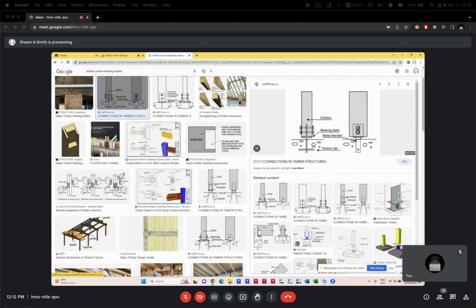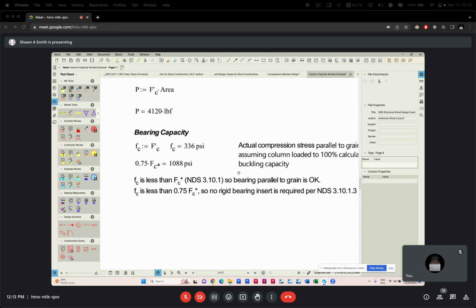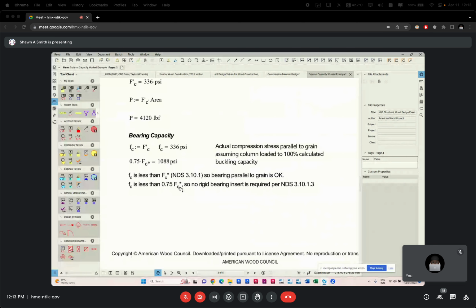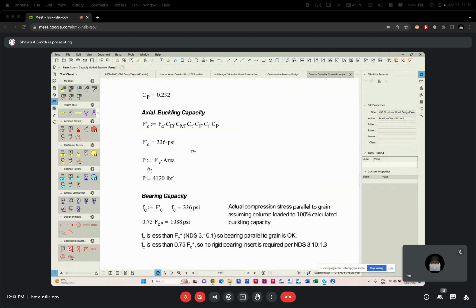It therefore means that you don't want the timber to be, perfect, here's one, you don't want the timber to be bearing directly down on whatever the support is. So you put some metallic inserts now so that the bearing is shared across a metal plate as opposed to just timber. Right? We don't have that luxury though here in Jamaica so much. So we might not get down to all this. All we know is that we would stop right here.